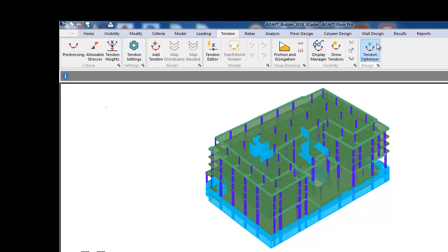The upper right is the story manager and help. So this allows us to quickly access the option to go to level assignment, active level up, active level down, single level mode, and multi-level mode. In previous versions, this was referred to as full structure mode. This has been changed to be referred to as multi-level mode for this particular icon.